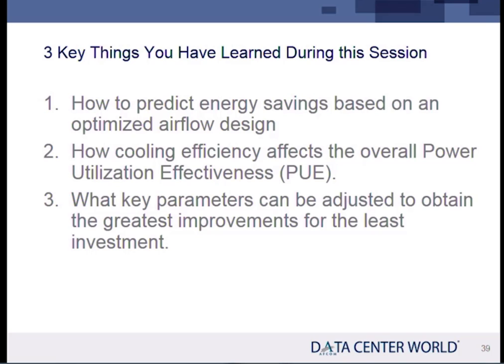Generally it's on a transfer switch because you want to keep that cooling system going in the case of down power. So it's sitting there on a transfer switch. You can go measure it. Ratio those two measurements. If they're not close to 4, if they're 3, if they're 2, if they're 1 to 1, you've got a lot of opportunity for savings that you can make with fairly modest investments.